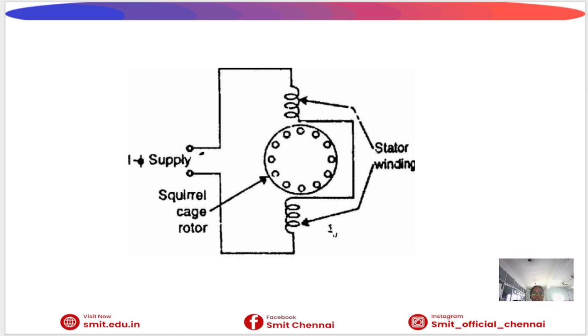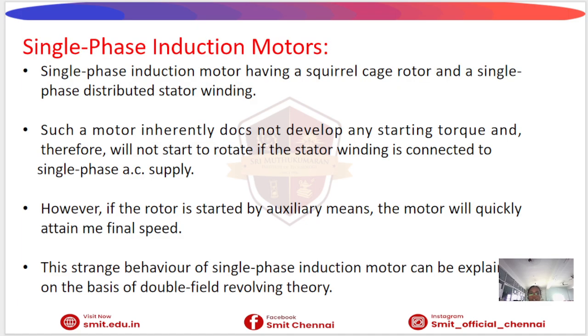Construction of single-phase induction motor. It consists of a stator and a rotor. The stator has a single-phase distributed winding, and the rotor is a squirrel cage rotor. When connected to a single-phase AC supply, the motor does not develop starting torque.